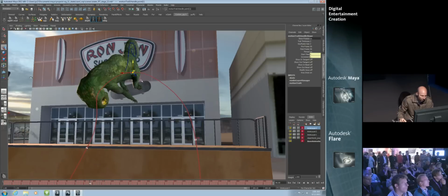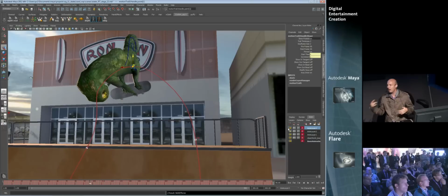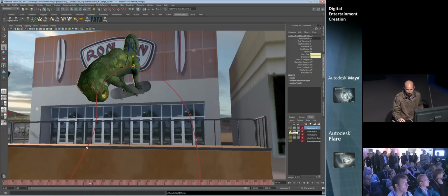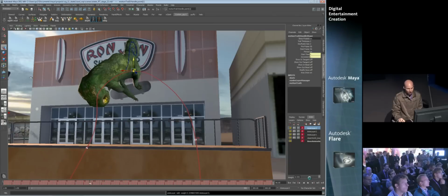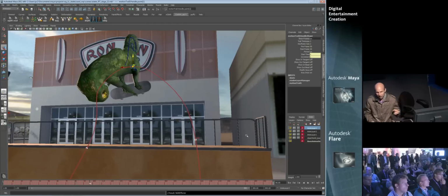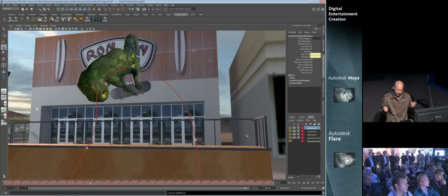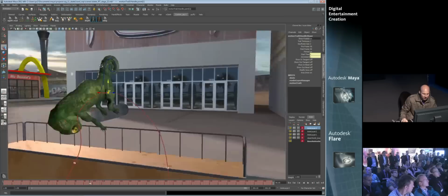It's really, really cool. The other thing that's nice about this is we did it on the animation layer. So the second advantage that I talked about previously is that I can turn the effect on and off. I can also adjust the weighting of that layer. So it's a very nice, fast, non-destructive way of taking dense data and editing it with a high level of control.